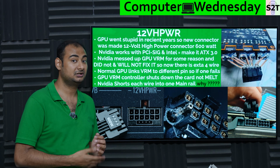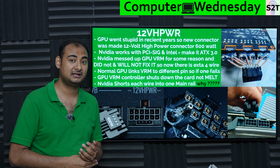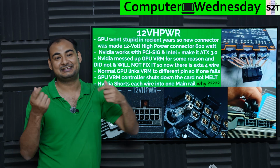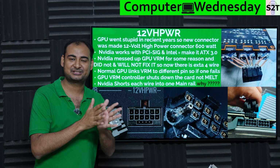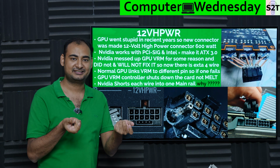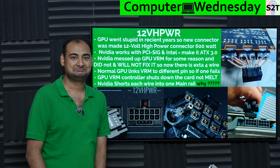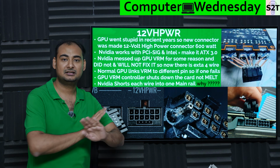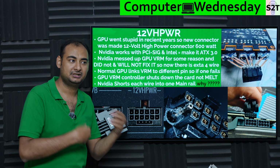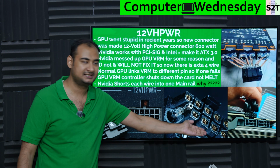And be mindful, by the way, older Nvidia, they were so anal about power balancing. They had MOSFETs switching these systems, meaning if for some reason you are getting like 80% and over, they will have current sense and they balance the load. In the modern system, everything is shorted to 1 point. Again, there is nothing wrong with shorting everything to 1 point, but have thick connectors.